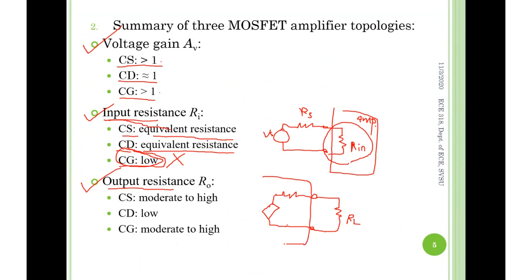Now this is the amplifier, and it has an output resistance here, series connected with the dependent voltage source. You generate this amount of voltage from your amplifier, and then it needs to be passed down to what? The load. So this time we care about how much voltage your load can receive.